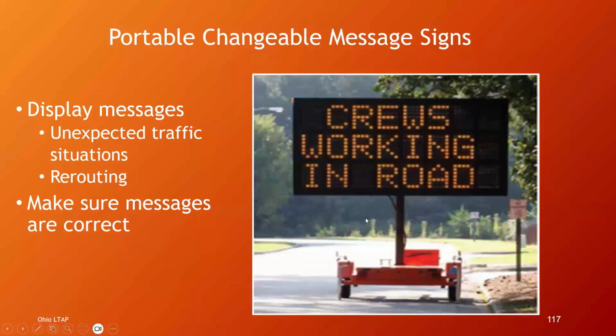This sign here says crews working in the road. Anytime you use a sign that lets the motorist know that the crew is actually out there working, you're enhancing the safety, because the studies show that if motorists are told that the workers are present, then they behave better. So, there's not just portable changeable message signs where you can say this. There's actual, optional signs to place with your other required signs to say workers in roadway and things like that.